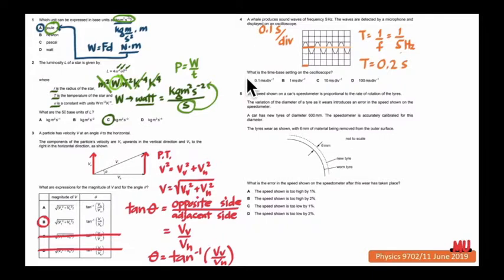Since the options are all expressed in milliseconds per division, we need to do conversion here. This 0.1 can be written as 100 over 1000, and 1000 here is 10 to the third power. When moved up to the numerator becomes 10 to the negative 3, like that, alright? This power is what we meant by the prefix milli. So we have 100, then this 10 to the negative 3 second, or millisecond per division.